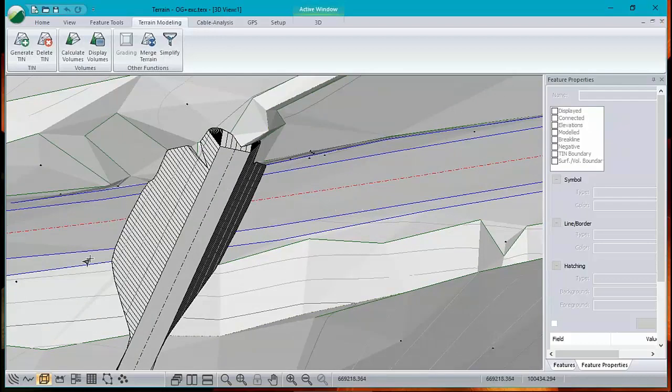Now I can build the fill. Now, ideally, we'd have a culvert in here, which would take up some space. And I'm going to show you that in a second. But I want to do the least amount of work possible to get some decent estimates of volumes and so on that you would use to maybe bid on a job like this.